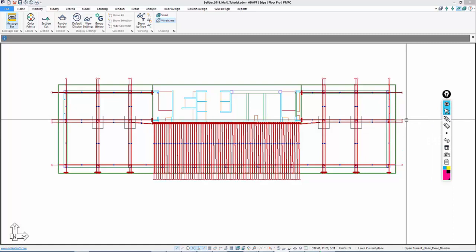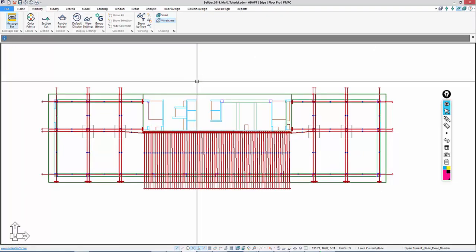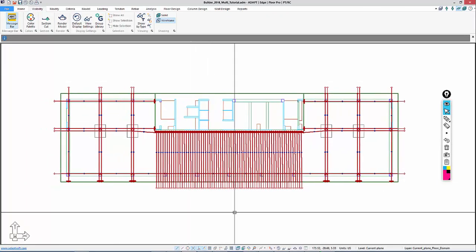We're now going to analyze the structure. So we've defined our load combinations. We've defined our strips. We've input our tendons. We now want to check pre-compression, stresses, balance loading. We're not going to go through each and every problem region within the slab, but we're going to pick one support line and take a look at that particular support line and just make some general comments about the results for the design. And we'll show also the use of the optimizer in this segment.